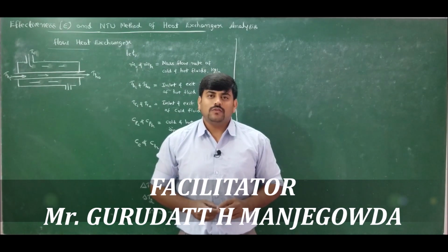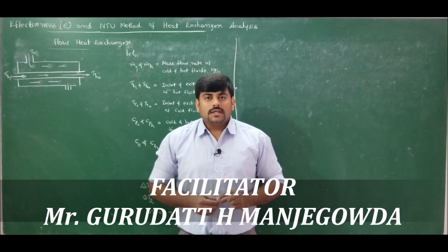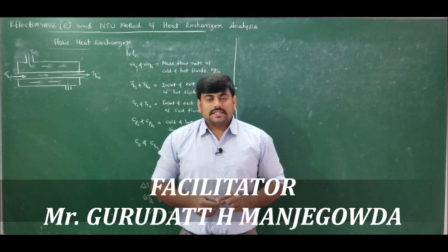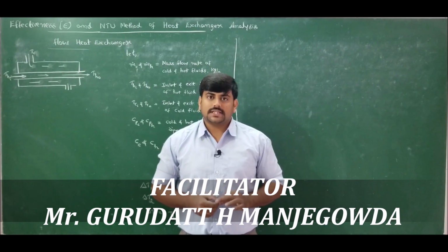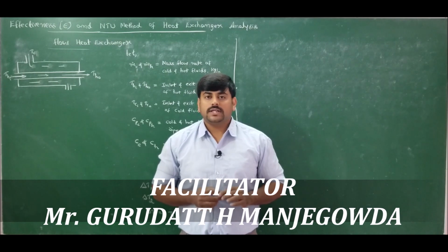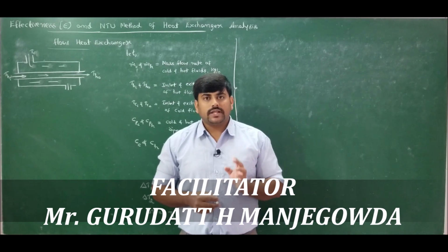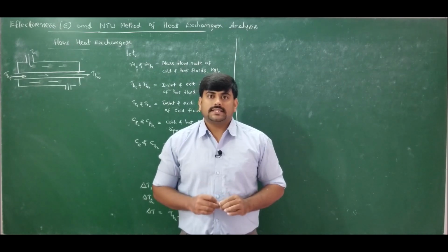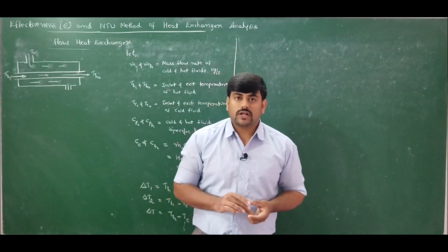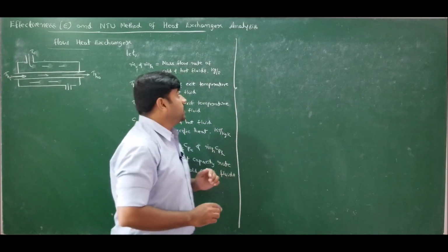In this final module we were discussing heat exchangers. So far we have discussed the effectiveness and NTU technique for analyzing the heat exchanger. In our previous lecture we derived an expression for the effectiveness NTU relation for a parallel flow heat exchanger. In today's lecture let us continue from the point where we stopped. That is, I am going to derive an expression for the effectiveness NTU method for a counter flow heat exchanger. Come, let us derive it.